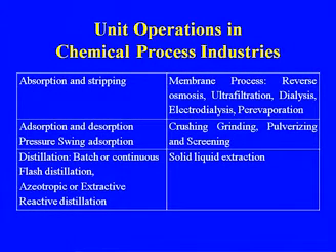That was the development in the case of adsorption, and now the separation of air is possible, because earlier we used to have liquefaction of the air for getting oxygen and nitrogen. Now, with the coming of pressure swing adsorption, we are able to produce oxygen and nitrogen even at a lower capacity. Distillation, that may be batch or continuous, flash distillation, azeotropic, extractive, and the newer development is reactive distillation, where simultaneous reaction and distillation both take place.